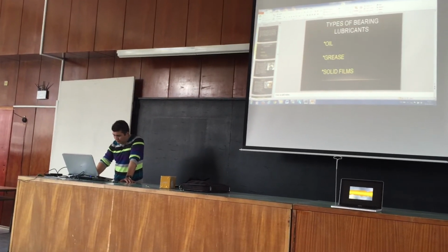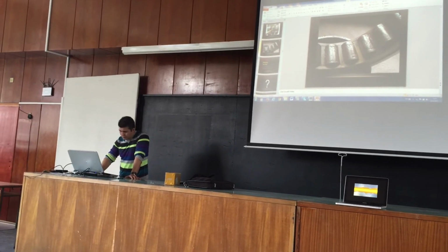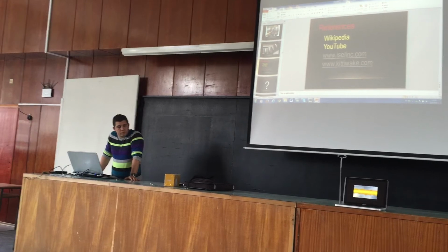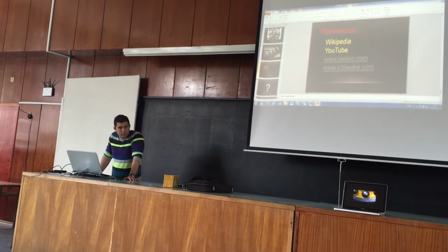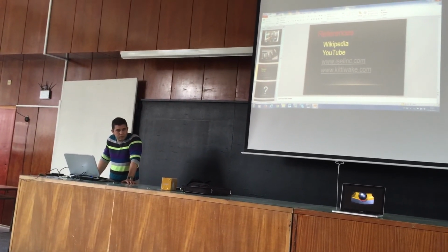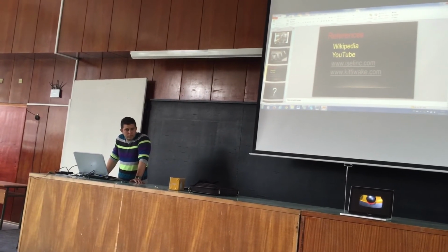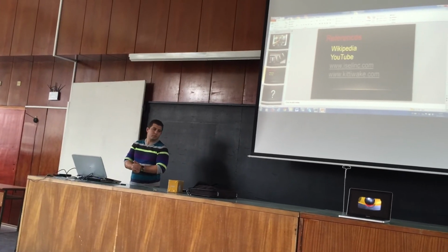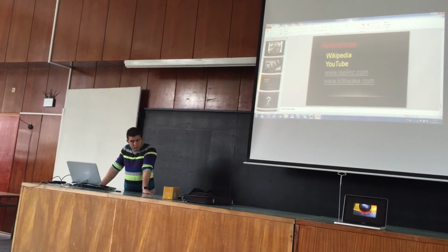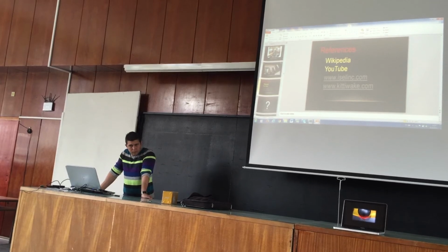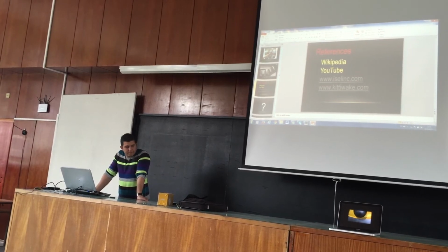A special kind of mixed film lubrication, elasto-hydrodynamic lubrication, or EHD, applies to conditions of extreme high contact pressures. Two things happen in EHD lubrication. First, the surfaces of the contacting parts deform elastically, spreading the load over a wider area. Second, the viscosity of the lubricant momentarily increases dramatically, increasing its load carrying ability in the contact zone. The combined effect is to trap a thin but very dense oil film between the surfaces. As viscosity increases, sufficient hydrodynamic force is generated to form a full fluid film and separate the surfaces.